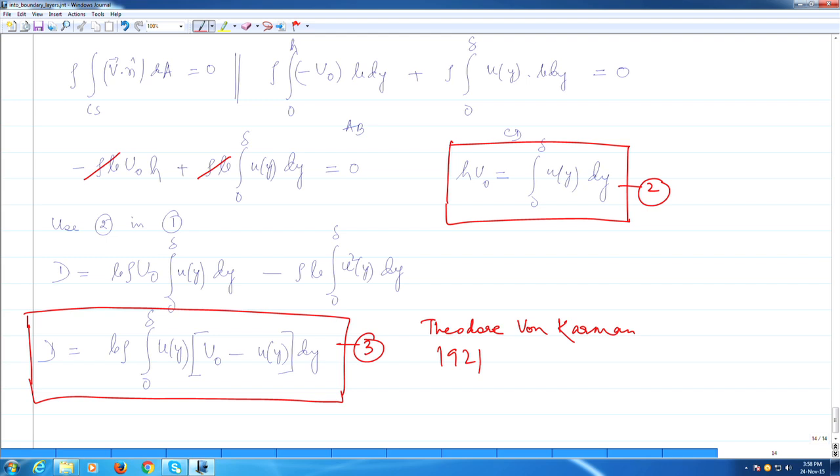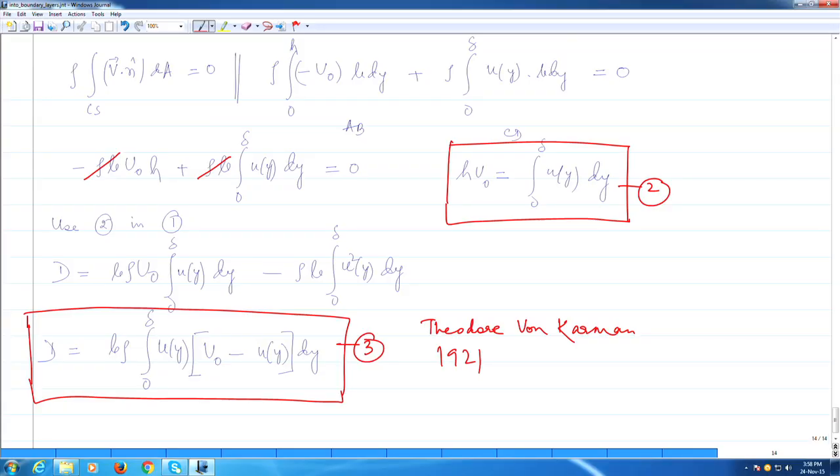So basically, we use a control volume approach, and we are doing an integral of the shear forces in order to get an expression for drag, right. So now, if you look at this, we should be able to find out this drag, provided we have some idea of the behavior of u(y). So, if we knew u(y), then we could easily get this. So, now the main thing is, how does the velocity, so what is the velocity profile, right. So, there we come down to that.